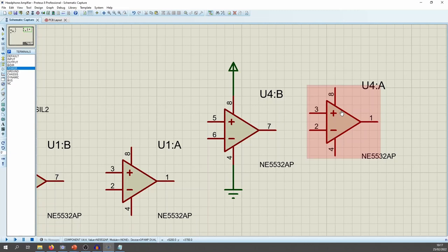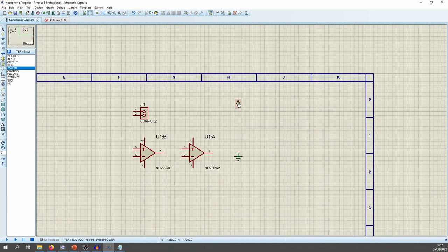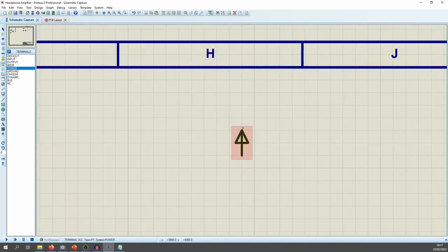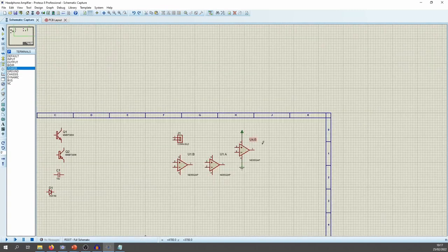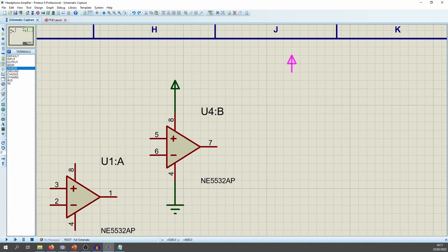I've seen that. On one page you would have all the power distribution to the ICs, and then on further pages you have the signal distribution. Well, you might put them on the same page as a different area. I see it most with big microcontrollers. But otherwise, all I would do for a big micro is just literally put the power net. It's more so all your caps are over on the side. The caps I do separately. So if I was going to do a bunch of decoupling caps, I would just literally put that there and then put a capacitor in the middle of this, and just have it close to it. You're not saying that this capacitor is connected, but you could potentially put a note there to say that these are decoupling caps for this chip, for example.